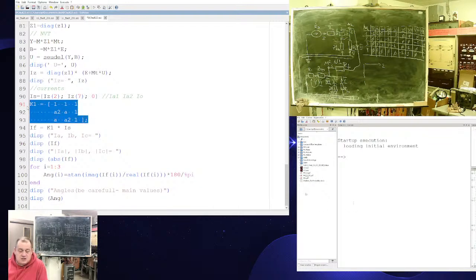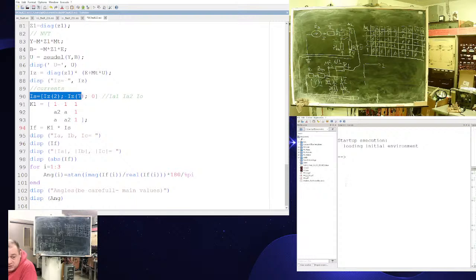What's this? What's this matrix? It's the matrix of the inverse Fortescue transform. Here I have a filled sequence vector. If I multiply the sequence vector with this matrix, I will get real currents. So I will get ABC currents of my transformer. My meters do not show angle, so to check with meters, I use the absolute value, because my meters show absolute values.